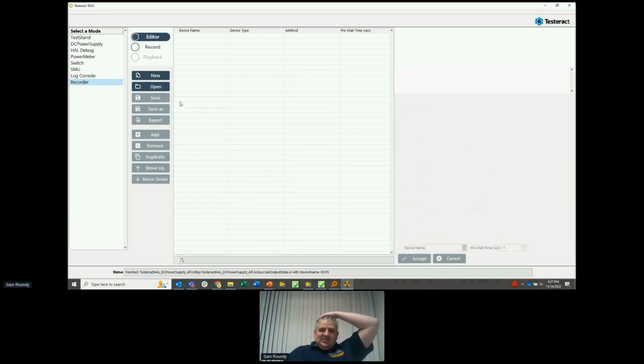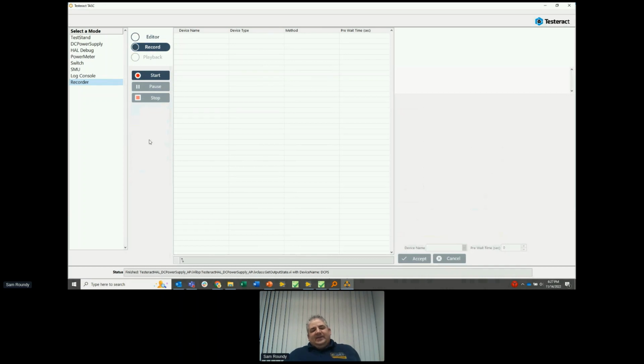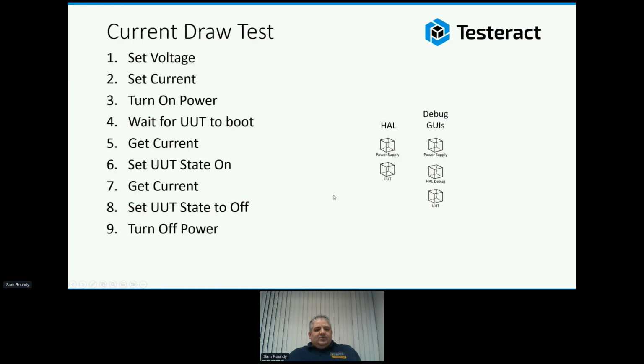You can click on this record, kind of like a macro in Excel. And so let's say that we want to create a current draw test, okay? So we're going to set the voltage, we're going to set the current, we're going to turn on the power, we're going to wait for the UUT to boot, we're going to get the current, we're going to set the UUT state to on, then we're going to get the current again. So we're going to get the current twice, once before we turn the full TX CCA on, and then once after, and then we're going to turn the TX CCA back to off, and we're going to turn the power off. And so really, if you look at the pieces that we need, a power supply HAL, a UUT HAL, and then we need the debug GUIs to do it as well.